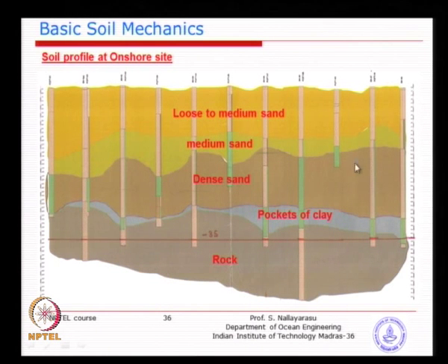So, basically with this, do we want to continue with the construction, where you want to finish the pile, whether you want to stop the pile here or here, needs to be decided. So, this gives information that the clay layer is going to potentially create a problem if you happen to terminate your pile in that layer.